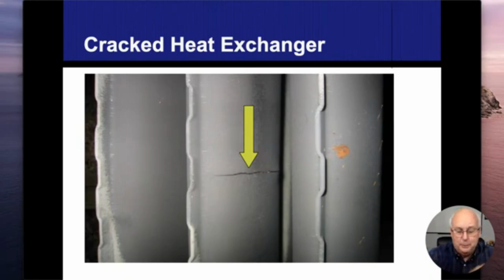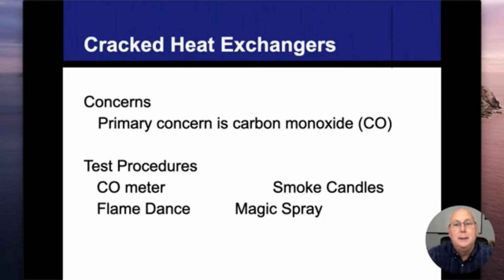Same thing with, let me back up a slide here, smoke candles. This is something I really don't recommend that you do. But you can actually put a lot of smoke inside the heat exchanger. If there is an opening in there, that smoke will pass through the heat exchanger as long as the blower fan's not running, and then that smoke might be coming into the house. But this is somebody else's home, and I'm not a big fan of putting that in there.